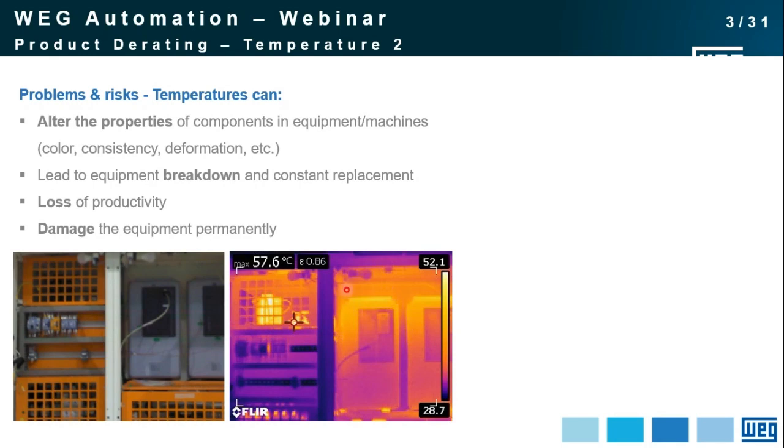And on the top of these VFDs, these variable frequency drives, the temperature is also very high. And this picture was taken with the panel doors open. So can you imagine how hot this panel can be once the doors are closed?